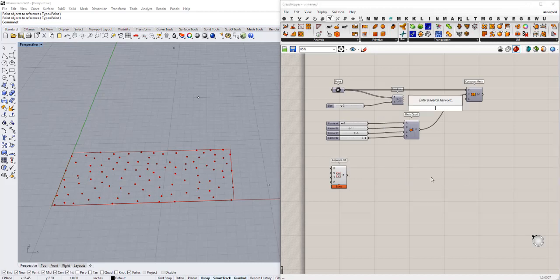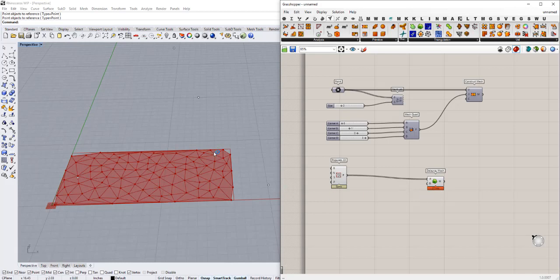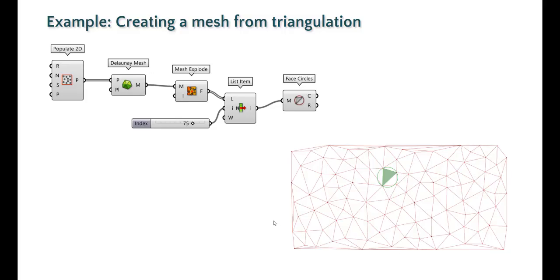What the Delaunay mesh does is it takes these points and a plane in which it's working with. That helps that all of these are planar because it can project down onto that its algorithm that makes that work. And so what that is, it'll take all of these points and it'll find 3 of them. And if it can connect a circle around those 3 and not include any other points, then it'll make a mesh face.